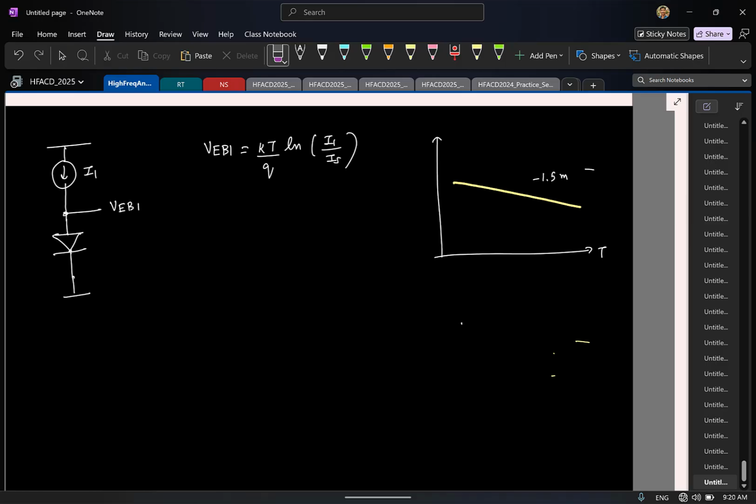So let us say this is the voltage you have right now. But finally, for your voltage reference, as I increase temperature, what do you want that reference to look like? It should remain constant. So let us say it should do something like this. Constant. Now tell me, I have some quantity which is reducing with temperature. I want to get a final quantity that should be constant with temperature. What do you think I can do?